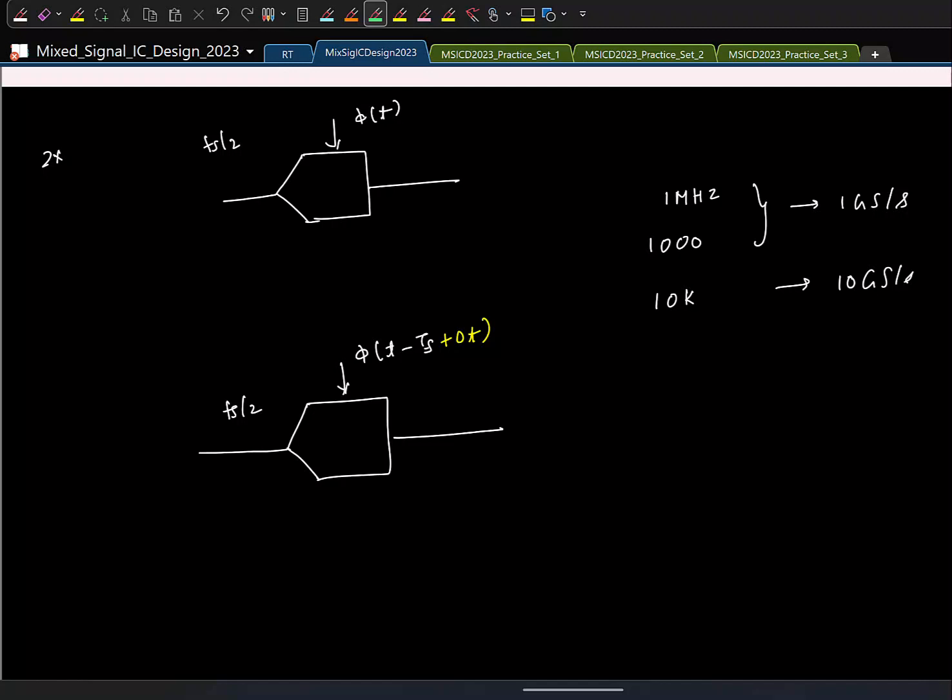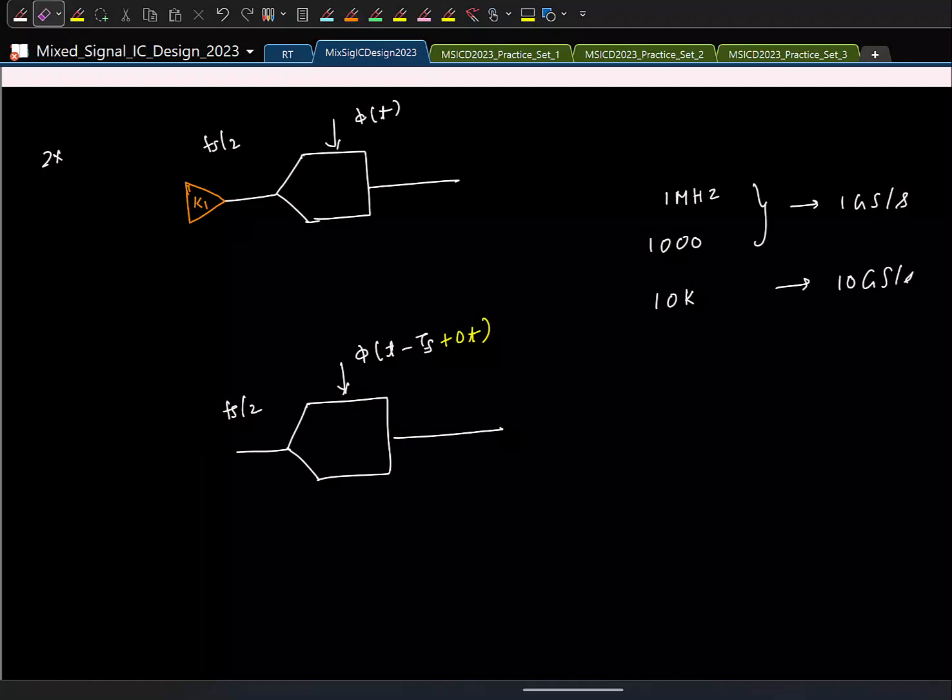So one straightforward thing that can happen is that ideally the ADC should directly sample the input with a gain of 1. Let us say there is a small gain error, and this is different for the two channels. In addition to this, any ADC will have some offset.